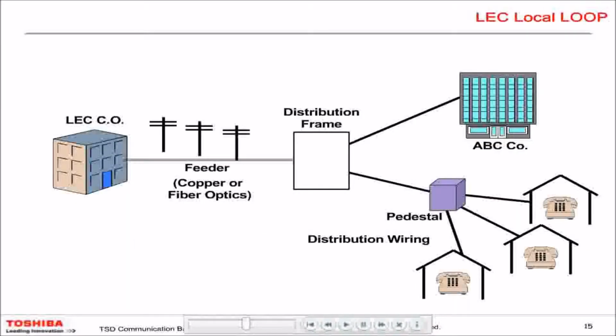The way telephones and or telephone systems are connected to the PSTN, or Public Switched Telephone Network, in a traditional network is via the local loop. There are a variety of facilities that can make this connection. The different connection types between your home or office and the LEC, local exchange carrier, offer different benefits. We'll talk more about the variety of local loop connections in the next session. In this picture, you see distribution channels connecting subscriber to feeder. Subscriber loops can be analog or digital. Feeder migration may begin analog and be converted to digital in the path along the way to the local exchange carrier central office.